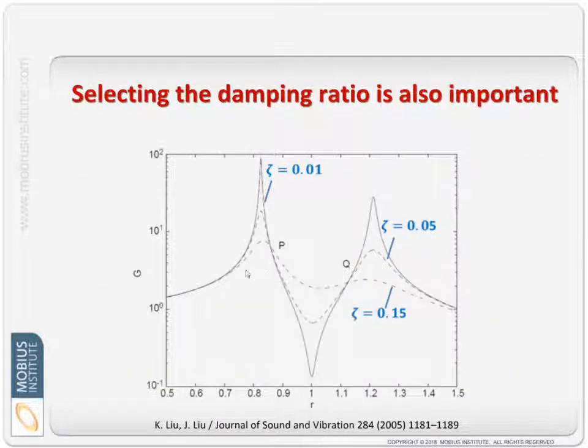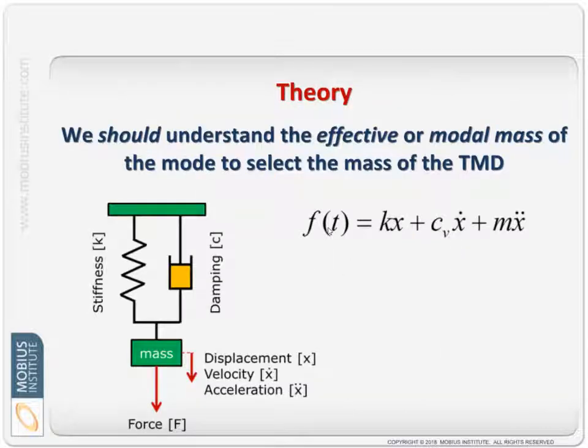So here, this was the case where it was very lightly damped. You saw that in the curve just before, and that would be the response of adding a single degree of freedom system to what is essentially an existing single degree of freedom system, and we end up with two modes. It's a 2 degree of freedom system now. But as we add more damping, we get a different response. So it doesn't attenuate as much right at the natural frequency, but it still does a pretty good job.